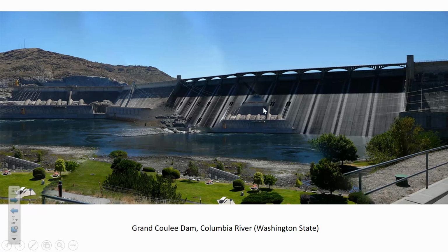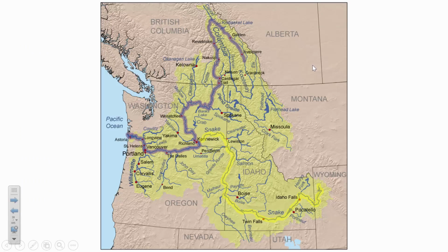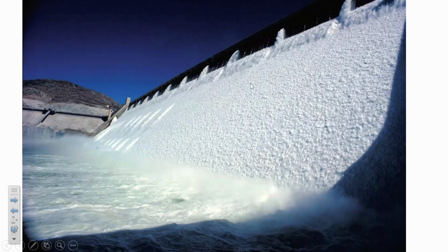So the spillways are only used very rarely, but when the water levels get high, it's much better to have an engineered method of the water overtopping the dam rather than for it just to happen on its own, where the water would be finding whatever the lowest point of the dam is and flowing over without a specifically engineered spillway.